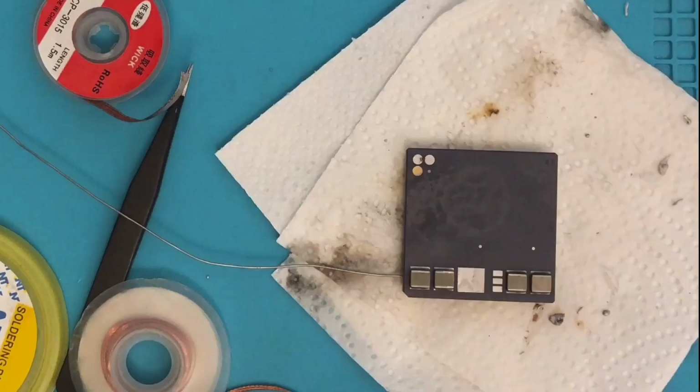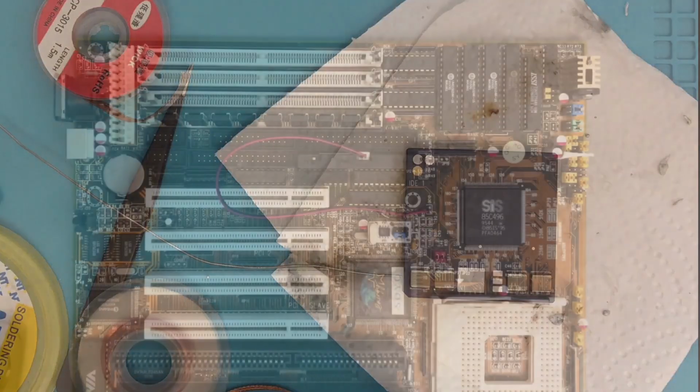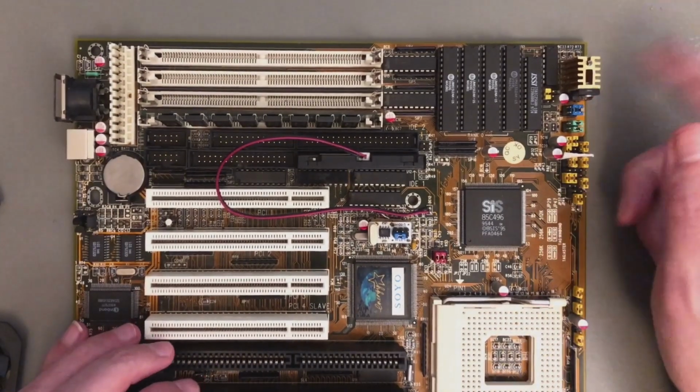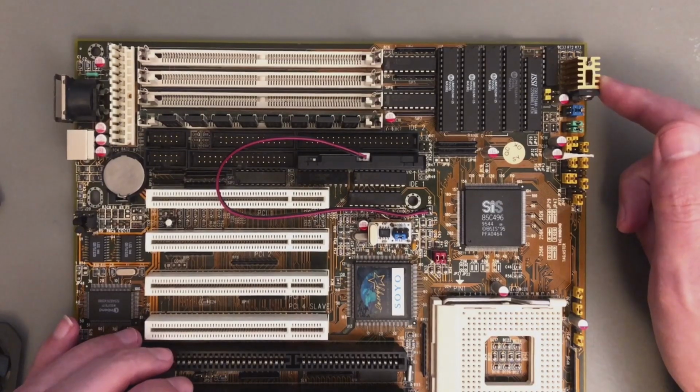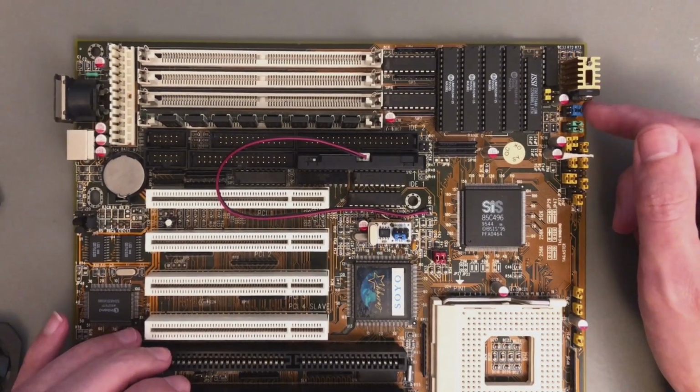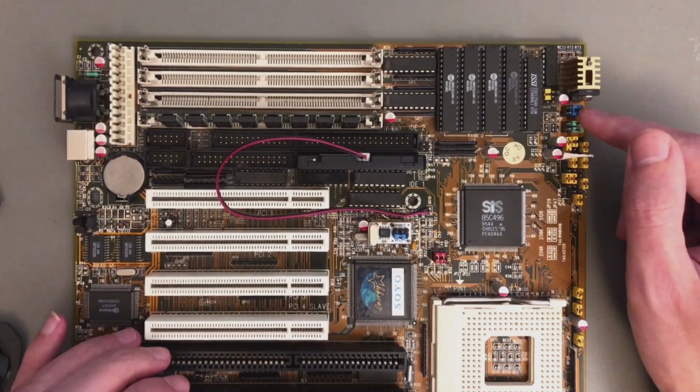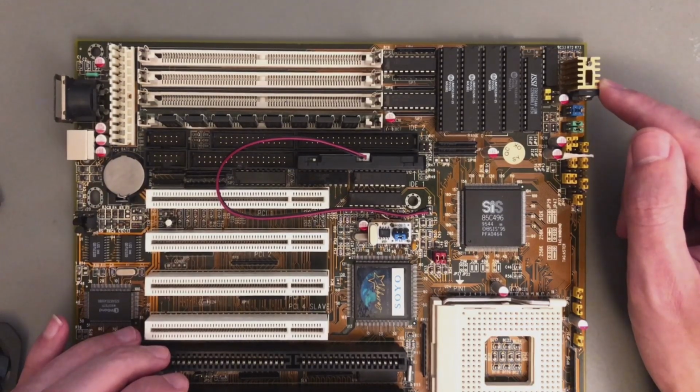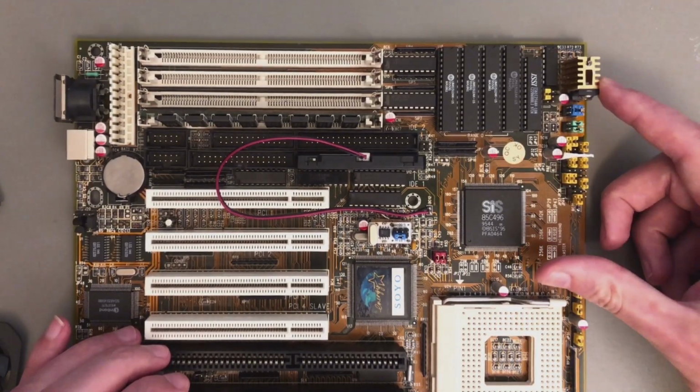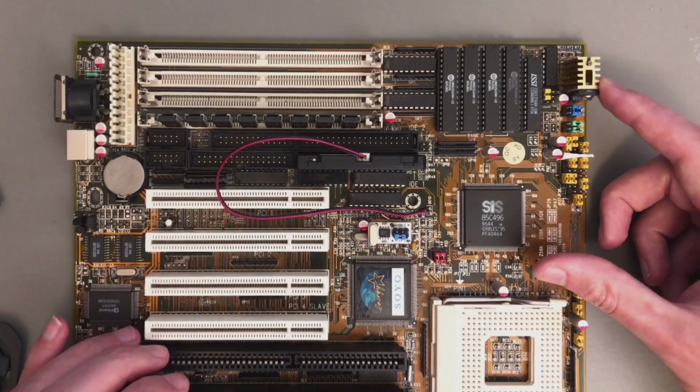So then, okay, we need an external voltage regulator. And of course my thought was to just use the voltage regulator I have on the motherboard. You see, last time we did a lot of modding here and now I have 8 very nice settings from 3.6 to 4.4. And this voltage regulator normally is rated to 2 amps, but can certainly do 3. Now the Pentium Overdrive, even at 100 MHz with 4 volts, is around 2.4 amps. So in general it is okay.